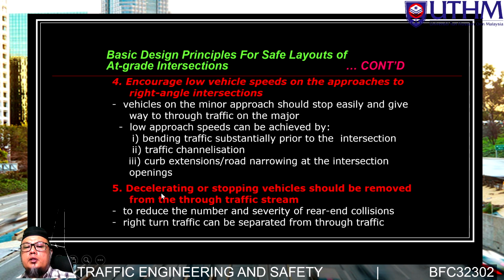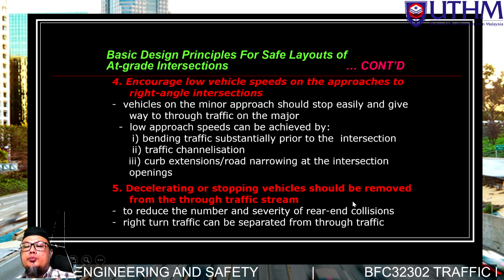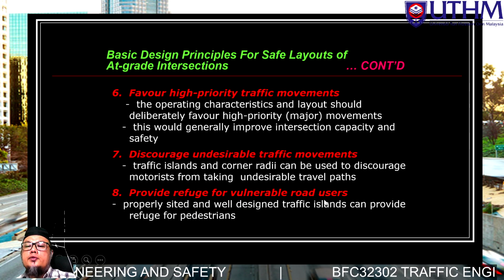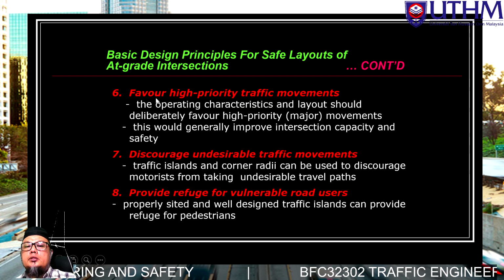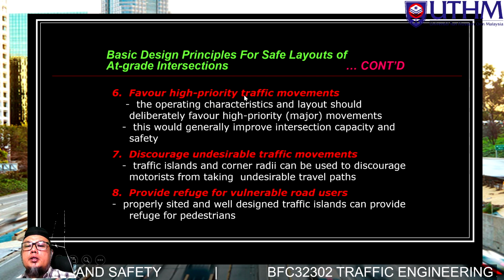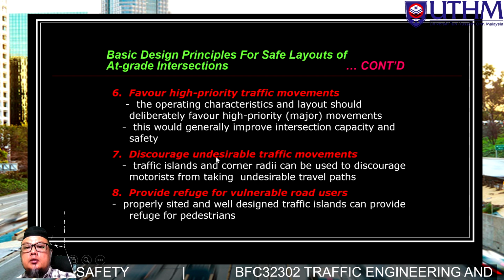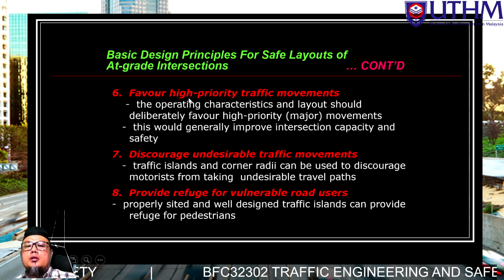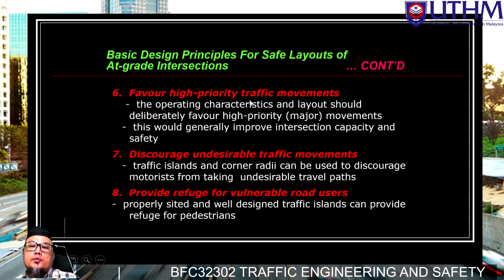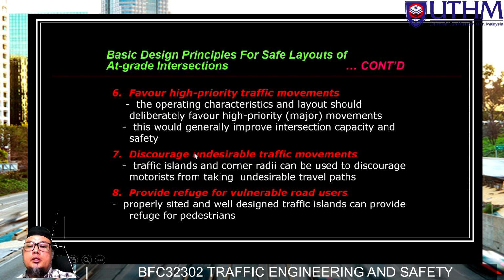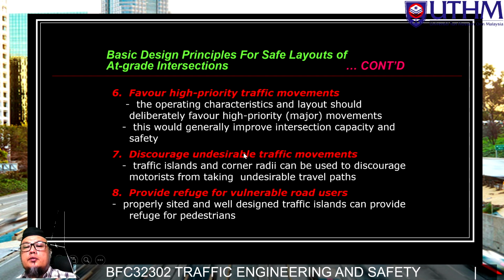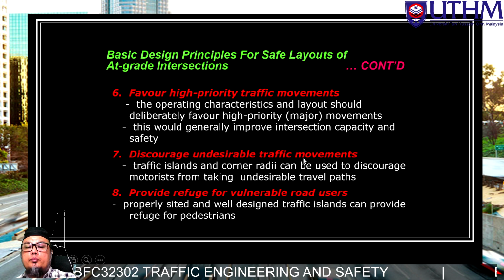Okay, five, decelerating or stopping vehicles should be removed from the through traffic stream. Number six, favor high priority traffic movement. This is typically like which approach or which type of vehicle is to be given priority. Okay, number seven, discourage undesirable traffic movement.